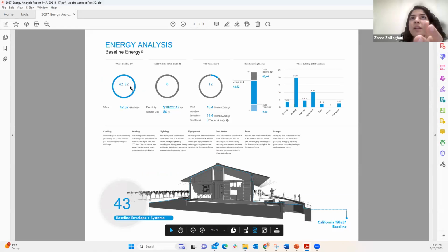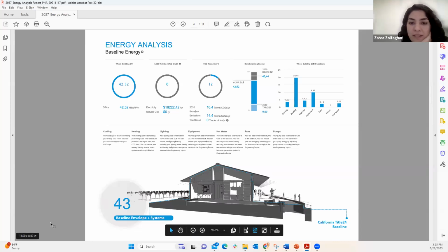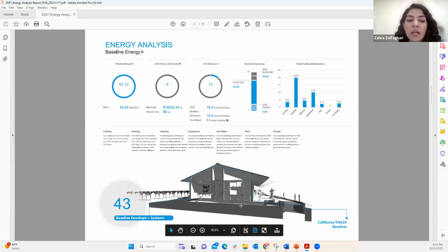So this baseline option shows the baseline energy use intensity, which is calculated based on the code minimum requirements, or the baseline requirements of the energy code that they selected or needed to comply with when they were setting up the project. As you can see, they added a 3D section of their geometry to point out the changes to the building characteristics and highlight the changes to the EUI. This really helps to better understand the numbers and what was the driver for these numbers.